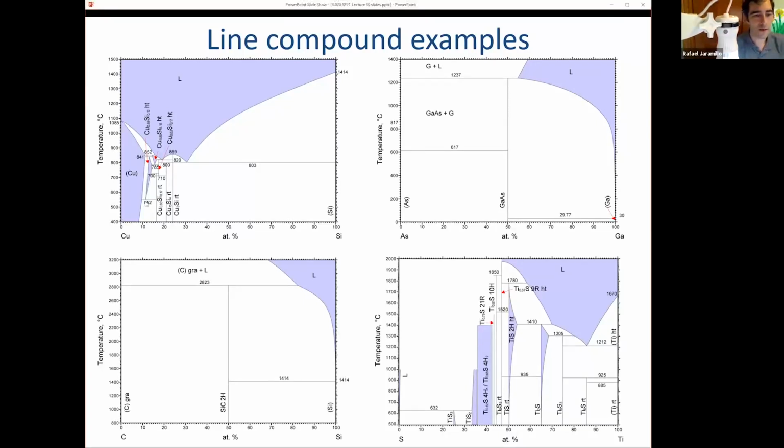But the thermodynamics here is that this is a pure phase, this is a pure phase, this is a pure phase, meaning it's always going to be a known composition, never going to be alloy. This is a pure phase, and this is a pure phase. They just appear as single points on the free energy composition diagram. That's what I meant to say.